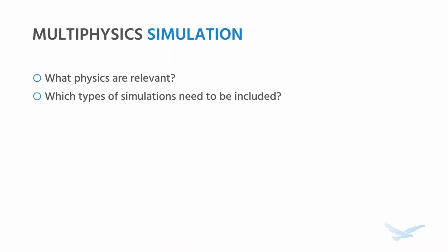Yes, Tim, sorry. I was just going to dovetail on that. I've always thought it's interesting how in simulation software we can separate our physics and find out what's important. Sometimes as engineers, we tend to overcomplicate things at moments. But in simulation, I take this crawl, walk, run approach where I can start by adding physics by physics to understand what's really driving the problem. I had a heat transfer one a long time ago that we thought radiation was really influential. And then by separating out the different heat transfer mechanisms, we actually found out that really wasn't a very viable cooling approach. And we had to look at some of the other heat transfer and convection in that case.